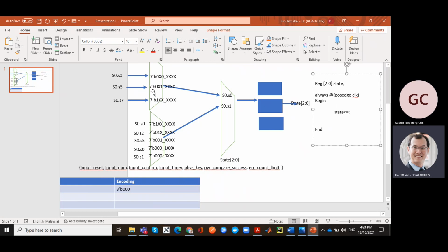You're setting the next state depending on two conditions. Okay, so basically the simplest is to put a case statement here. So the simplest is a case statement. You can do a nested case statement. That's fine, right? So the first case statement will be this 7 state. The next will be this.